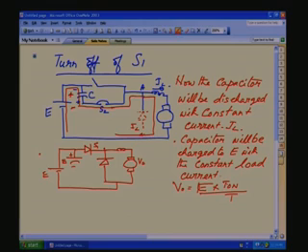Now we have two values to find, L and C, so two conditions are required. How to find C? Let us start with C. We introduced the C in the circuit so that we can force a voltage across the thyristor to switch it off. That is force commutation. We assumed in the previous analysis that S1 will commutate immediately.